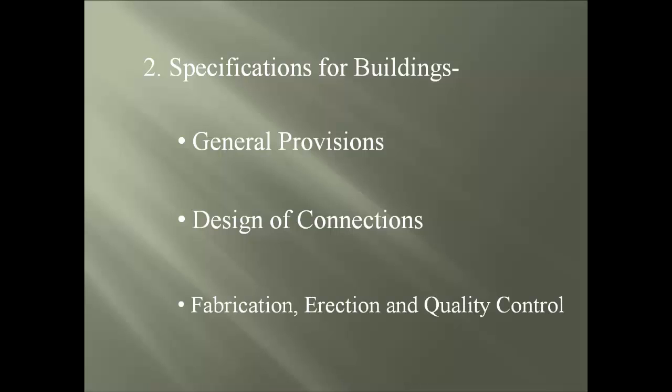And the last item is the fabrication, erection, and quality control for the shop. A quick tip is, both the shop and erection drawings shall clearly state the difference between shop and field welds, plus the pre-tensioned and slip-critical bolt connections.